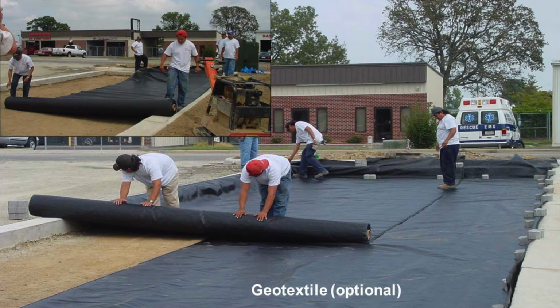If you do use them in the bed, overlap them 12 inches. In real fine-grained soils, use 24 inches of overlap. This here is a little bit more than a 24-inch overlap. Typically, it's cheaper to just use another roll than to cut, so it all depends, but there is a lot of waste going on there.